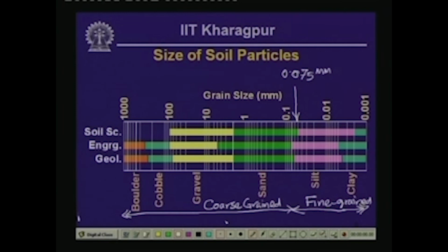Even finer is sand size particles, which begins from an equivalent diameter of about 75 micron to about a couple of millimeter in size. And if you go even finer, you end up with silt or clay size particles, as is shown on the plot there.